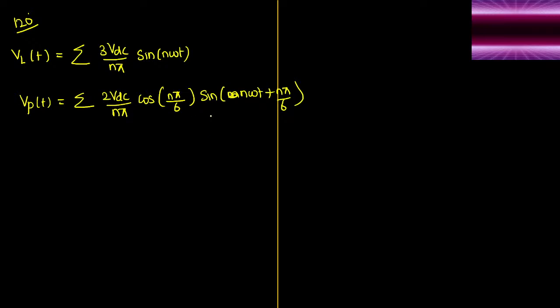That is very important. Okay, sir. This is the fundamental. This is in terms of trigonometric Fourier series expansion. Now we will write one more form directly. If a waveform is given, from the waveform, how will you calculate the output voltage? So the output phase voltage for 180-degree mode of conduction, again with the 180 general expression. It is not in terms of trigonometric Fourier series expansion. Just we have the input voltage and what can be the expected output voltage. That is going to be supply voltage into root 2 by 3. This is V0 phase voltage.